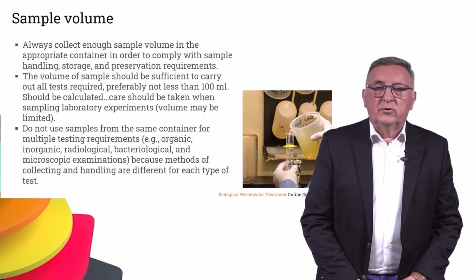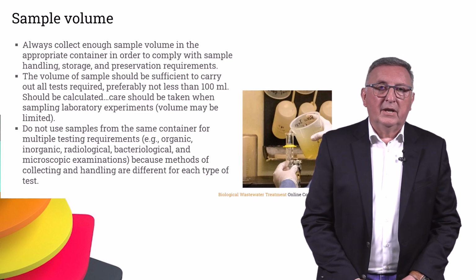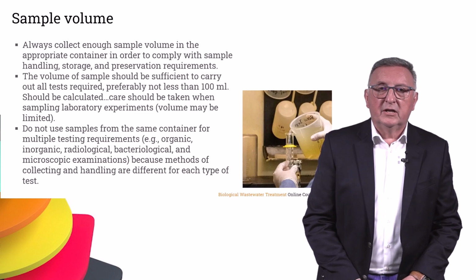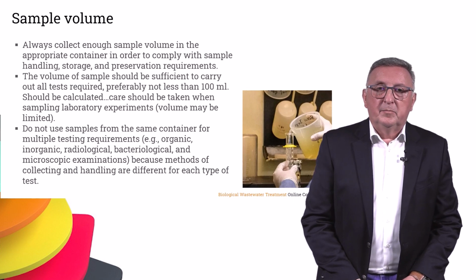Sample volume is an important parameter to consider. You always need to collect enough sample volume in the appropriate container in order to comply with sample handling, storage, and preservation requirements. The volume of sample should be sufficient to carry out the required tests, preferably not less than 100 milliliters. But this should be calculated.